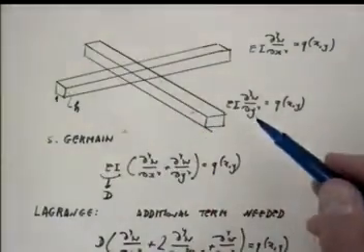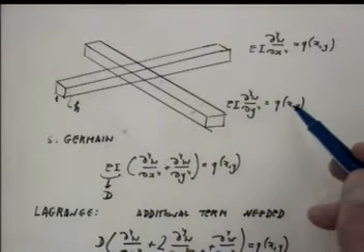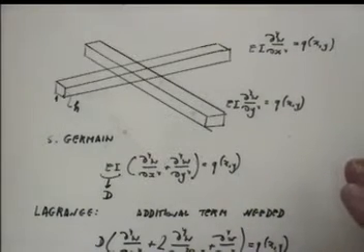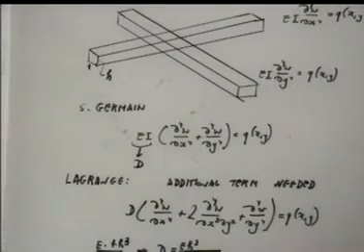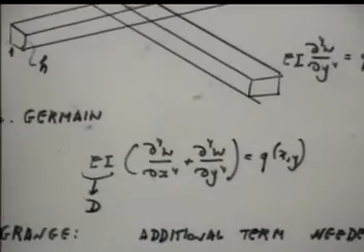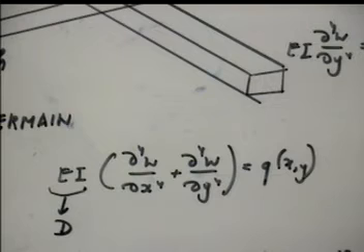Therefore, the same thing should be done: EI d4w/dy4 equals q, she said. Therefore, says Miss Sophie Germain, the equation should be the sum of these: EI (d4w/dx4 plus d4w/dy4) equals q of x. Very simple reasoning, very transparent, I would say.